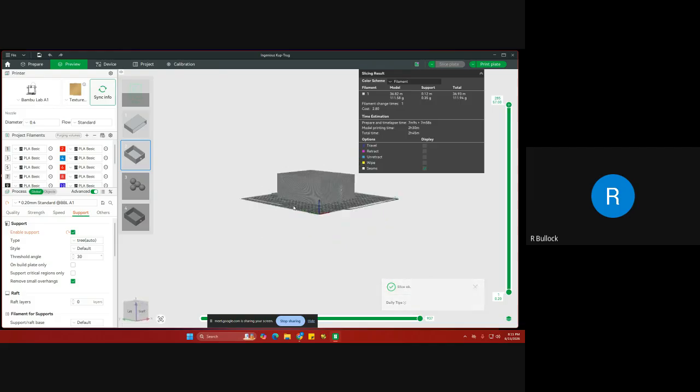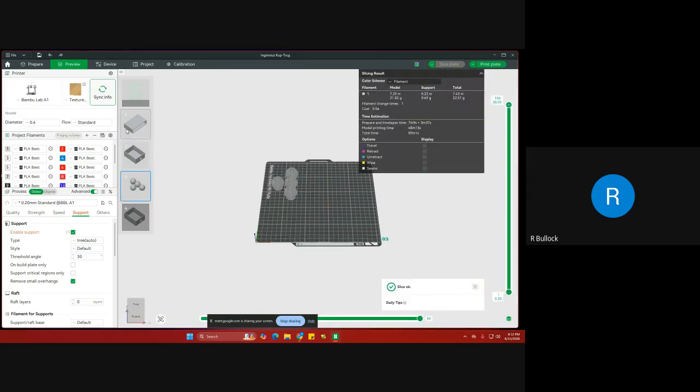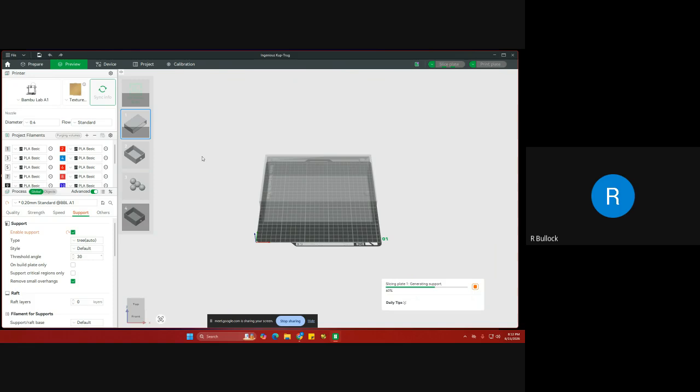The reason it needed supports was because we put the knob on the front. This is a moment where I'm able to show you the difference. If we print with the knob, you see it needs supports. But if we came in here and printed this drawer without the knob and printed the knob separately, it wouldn't need supports. And that's it. It takes, what is this, I think I saw 5 hours. So 5 hours for this piece.